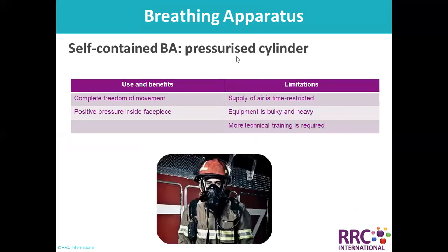And self-contained breathing apparatus, or pressurized cylinder, look at the picture even. It's a complete freedom of movement. That's why for rescue operations or for inspection of confined space, or even for firefighters, normally we use this self-contained breathing apparatus, because it has positive pressure inside face piece.